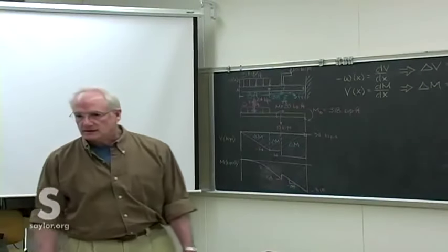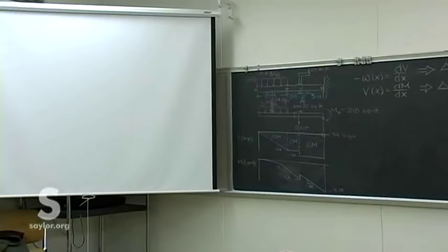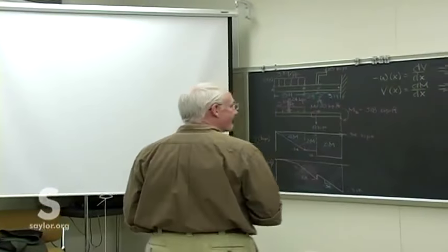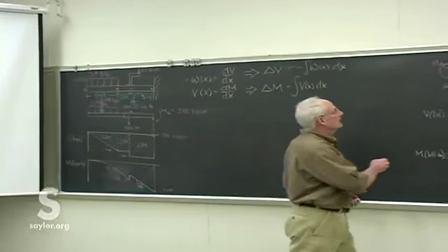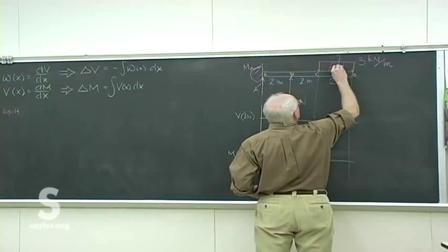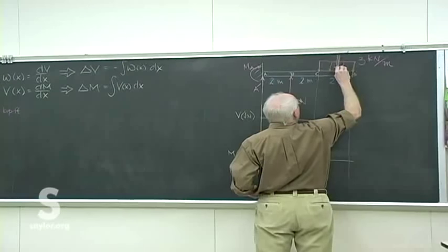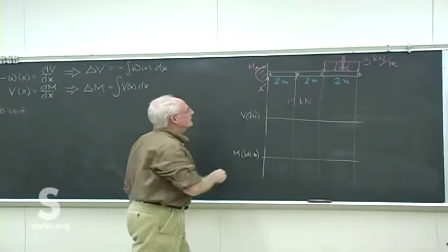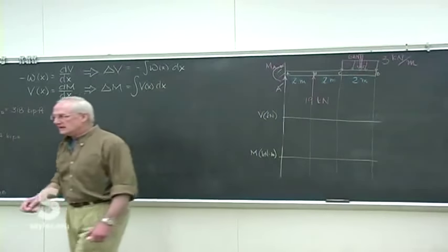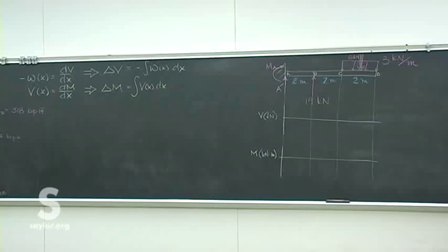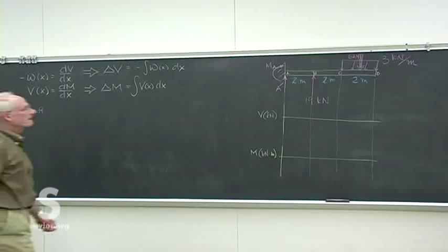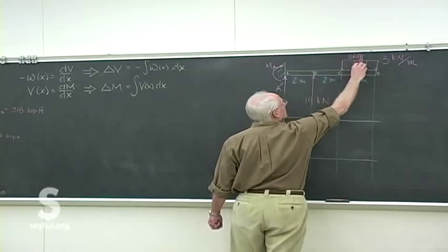Now, be careful. A lot of you are missing something. Remember, we can replace this with an equivalent point load of 6 kilonewtons. But that's only for the purposes of finding the reactions. Once you've found the reactions, you're done with that equivalent point load there.